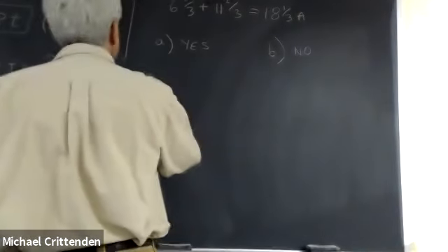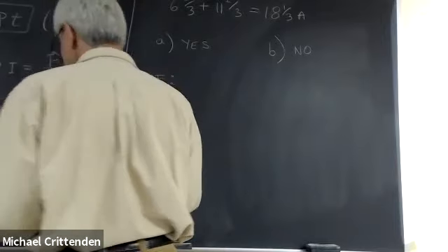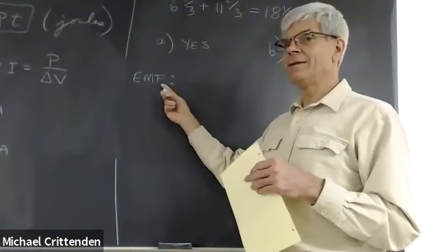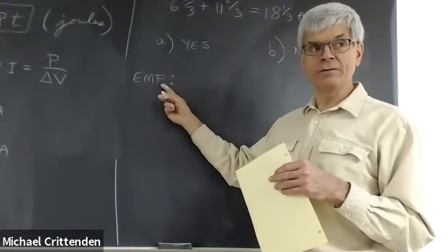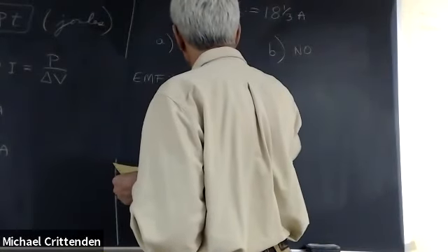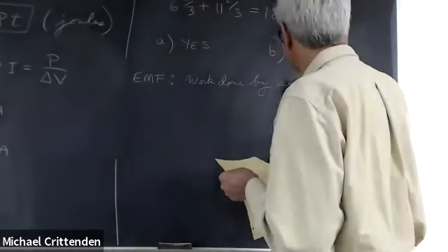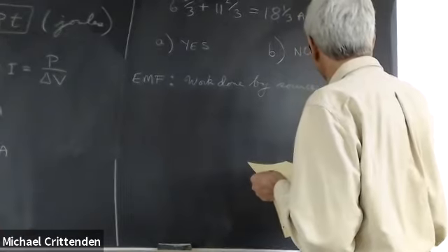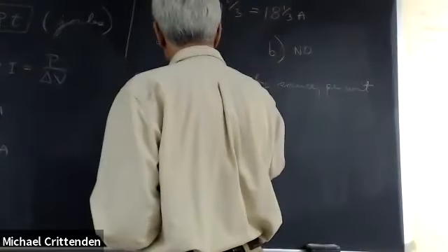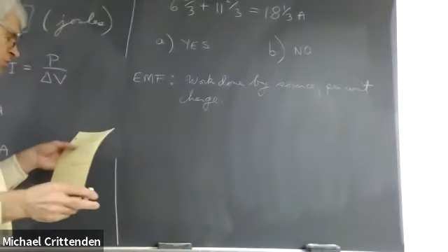So EMF stands for electromotive force, but don't be fooled. It's kind of an unfortunate name. Don't be fooled by the name. It's not a force. It's not measured in newtons. It's measured in volts. The work done by the source per unit charge.